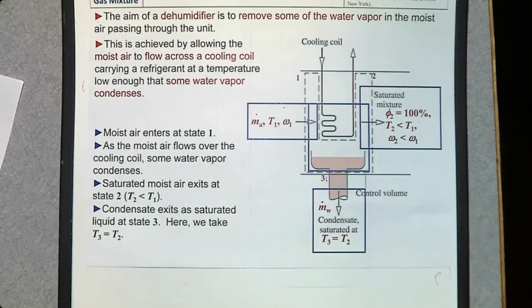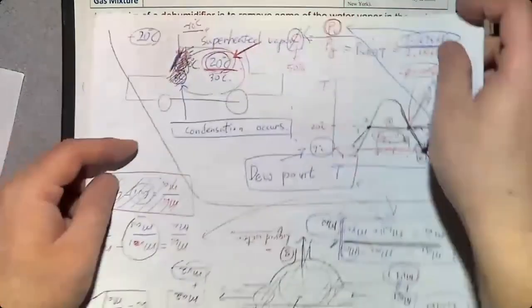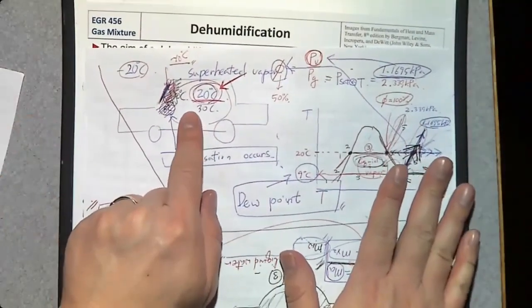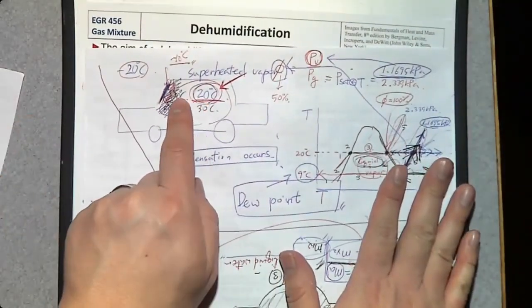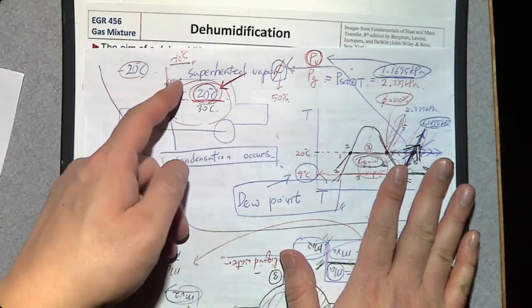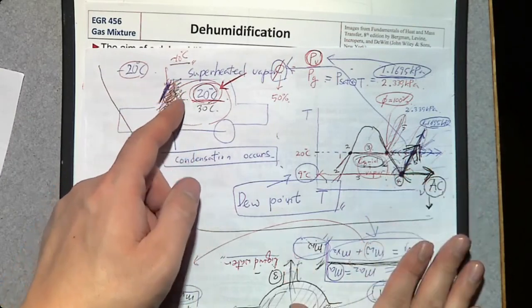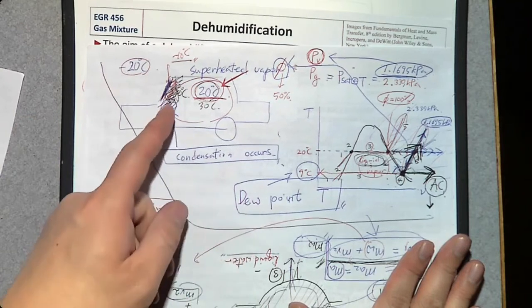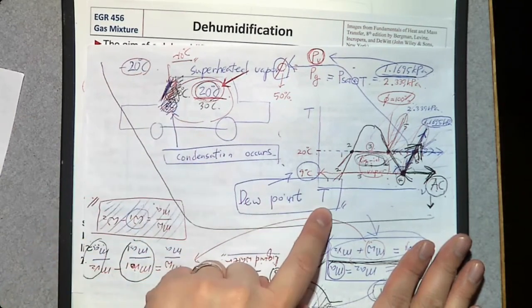So basically, to have the condensate, we need to reduce the temperature of the system. If you don't remember, please look at the example, where because of the temperature decrease near the windshield, the temperature becomes lower than this dew point temperature.